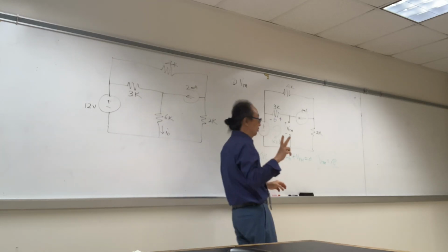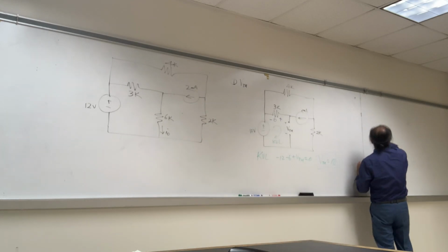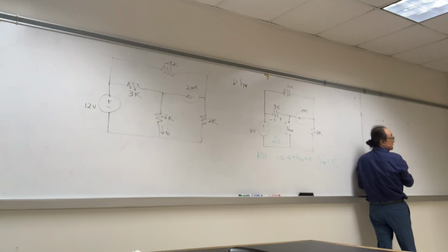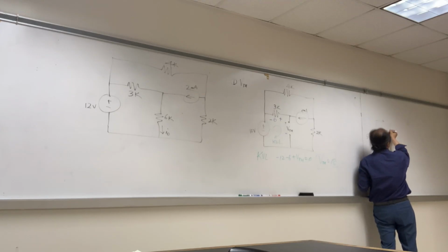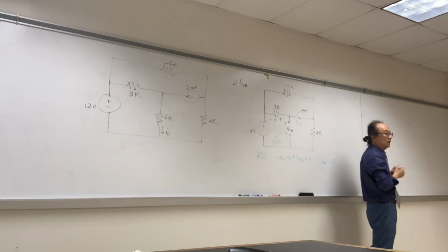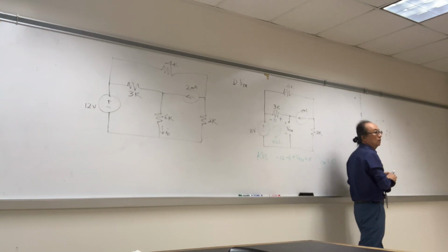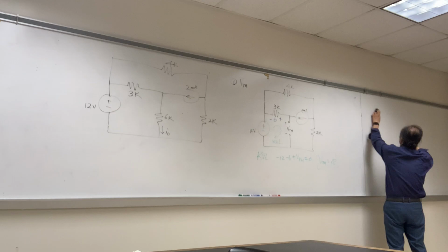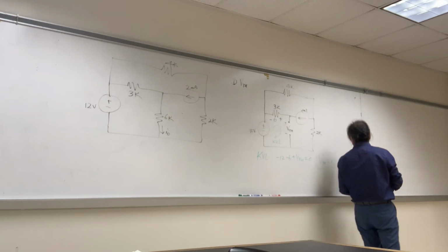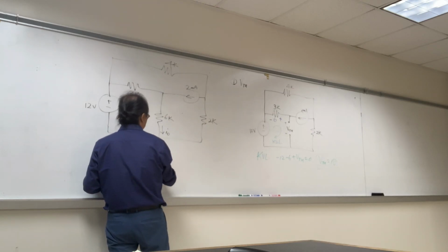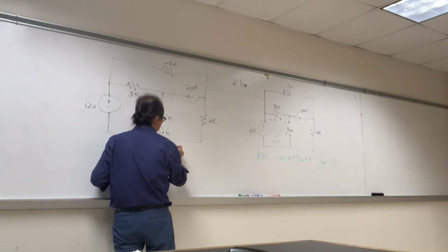So you need to remember two things in the given circuit. When we have a single loop, the current goes from higher potential to lower potential. That makes sense because the polarity of this one has to be higher potential to lower potential. Since they are parallel, it has to be 5, right? And then when you do KVL, 5 minus 5 equals 0. So those are the two things: the current goes in that direction, and then the polarity of those two. So we found VTH. We have VTH equals 18 volts.